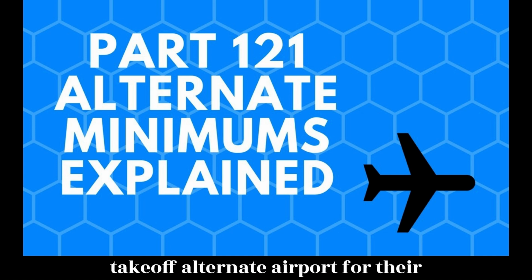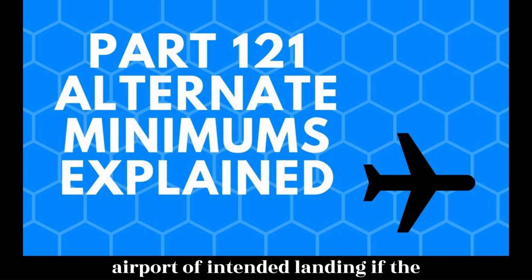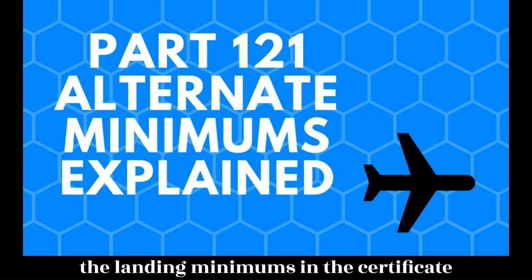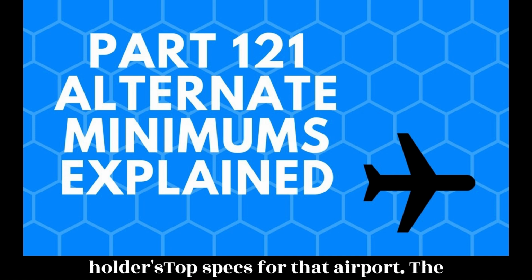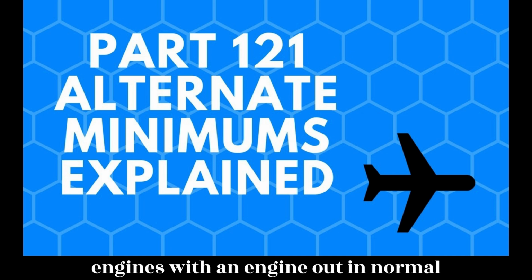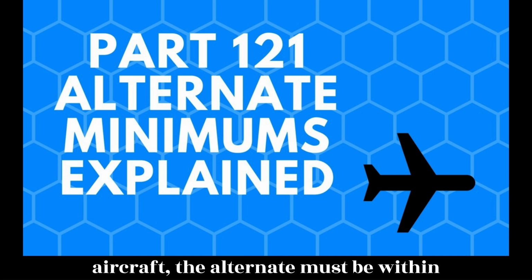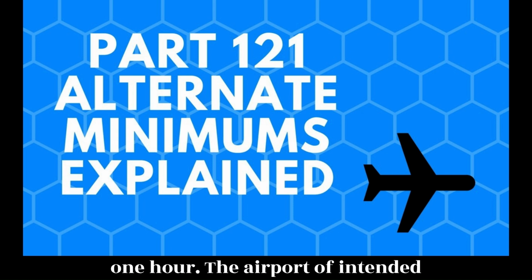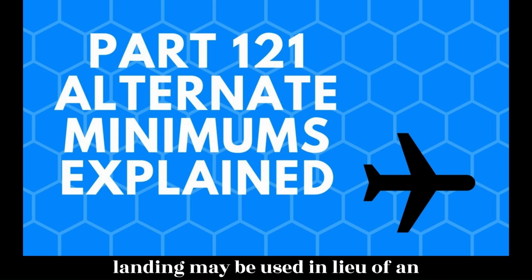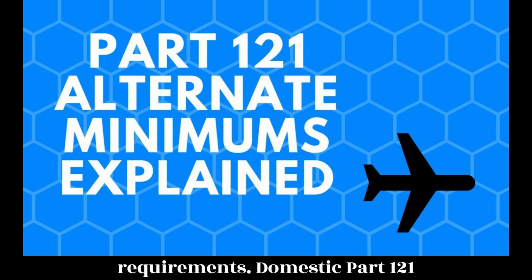121.625 to have a takeoff alternate airport for their departure airport in addition to their airport of intended landing if the weather at the departure airport is below the landing minimums in the certificate holder's opspecs for that airport. The alternate must be within 2 hours flying time for an aircraft with 3 or more engines with an engine out in normal cruise and still air. For 2-engine aircraft, the alternate must be within 1 hour. The airport of intended landing may be used in lieu of an alternate provided that it meets all the requirements.